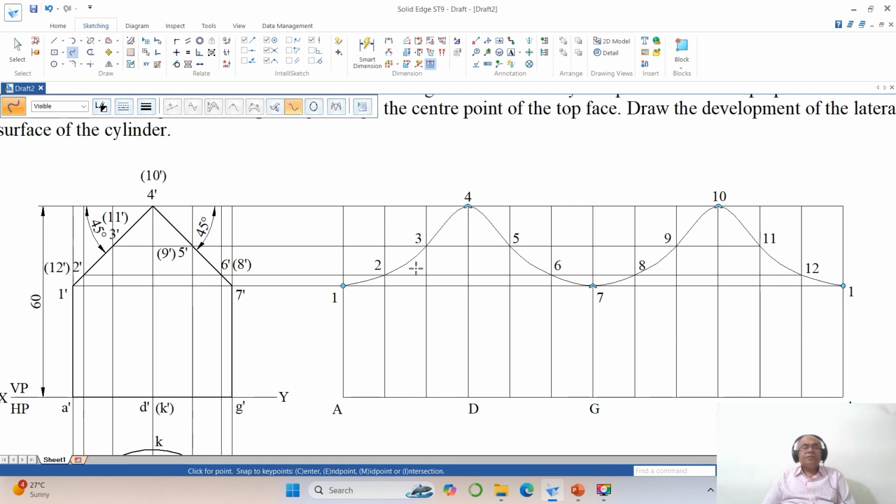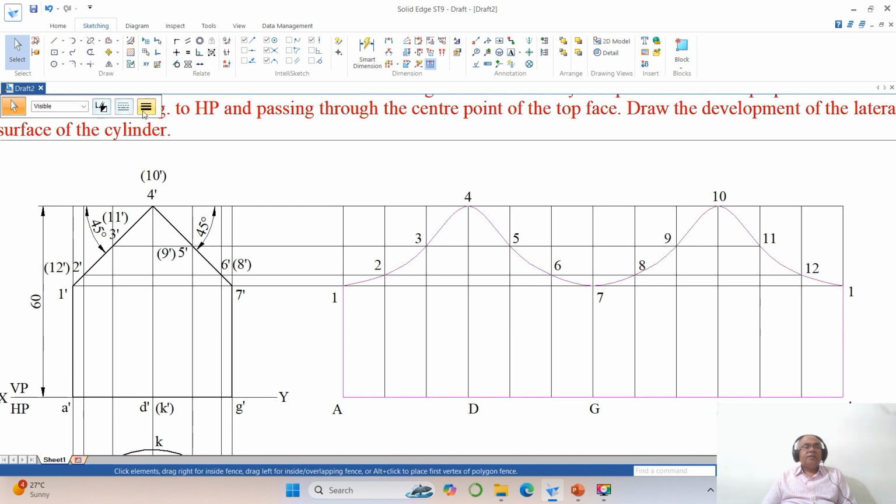Right click. Then you have the split, split this line till here, then split this line till here. Now you go to select, by holding the shift key, you select all these 3 lines and this entire curve and make it as 0.5.